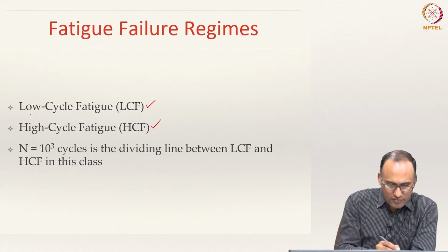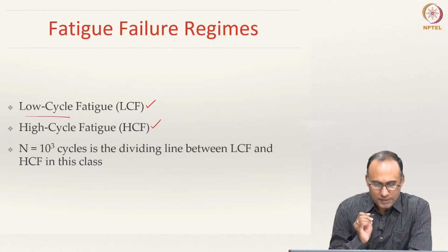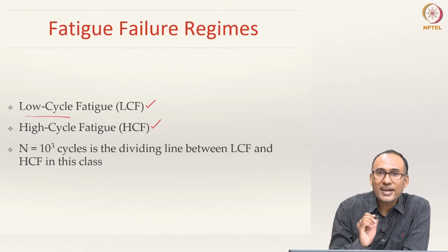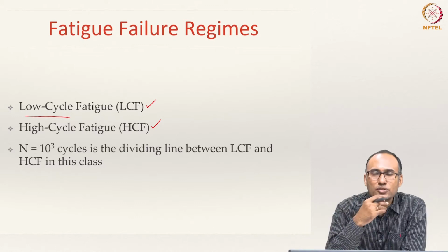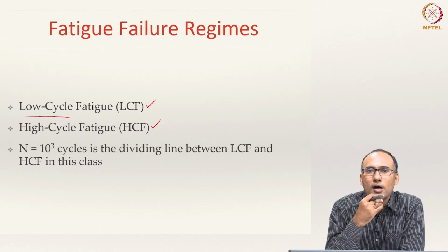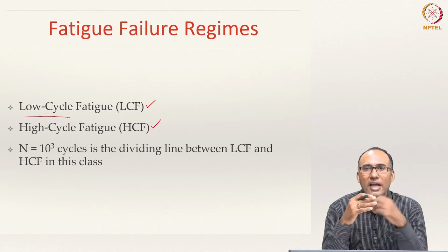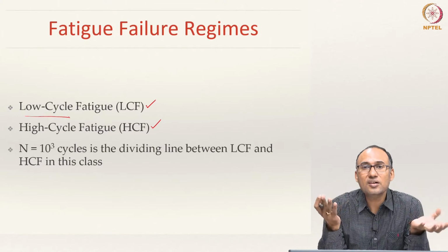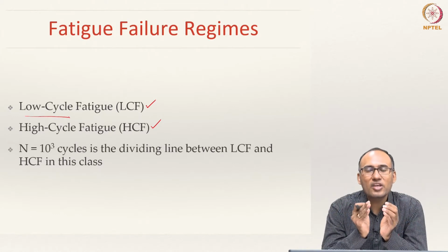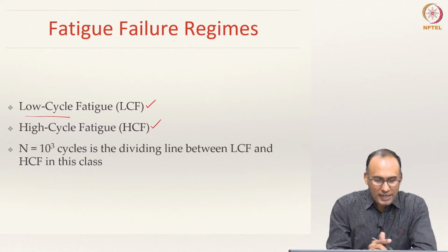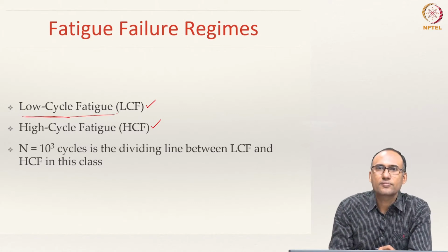Low cycle fatigue, from the name, implies that the component actually fails by operating at higher stress amplitudes, but a lower number of cycles. That means it will actually fail in fewer cycles. The number of cycles that the component is going to be serving us will be low, and that is why it is called low cycle fatigue.